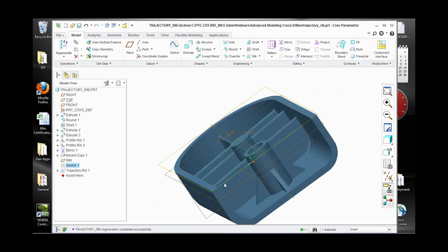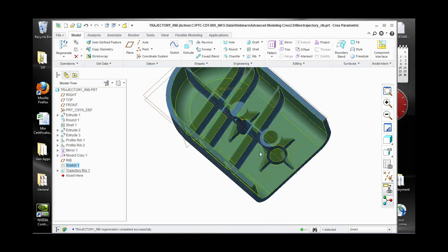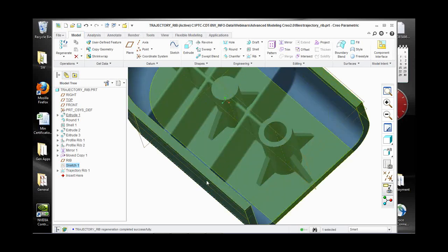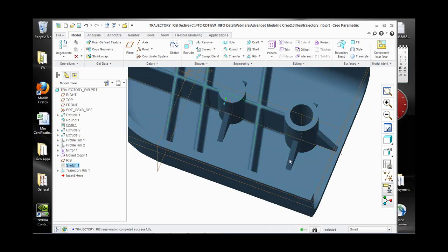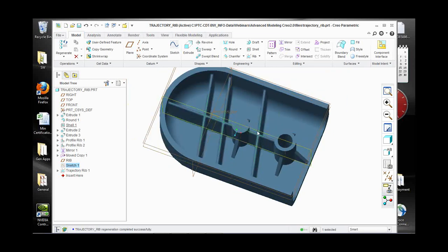Also, it intersects by pushing that curve out to a surface. So if I had created a curve somewhere right here and it didn't intersect or connect to a surface, this would fail. So it pushes out to, essentially it has to be in a bathtub, if you think of it like that. It has to go out to the edges of the bathtub, and it has to be at or below the water line of the bathtub for this to work, okay?